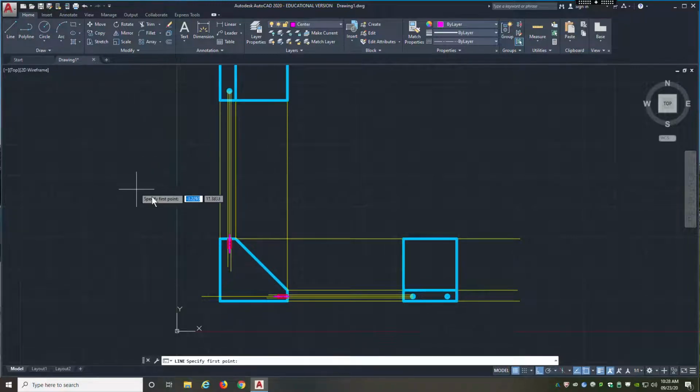I'm going to draw a line, and I'm going to turn my ortho off for a moment, and I just want to get a sense of where, right? If it's somewhere out here in the middle, I'm looking at about 14 inches, 15 inches where I can draw that. So 14, 15, let me get it clear out of the way. I'll draw 15 inches. All right, so turn my ortho back on, and I'm going to offset 15 inches.